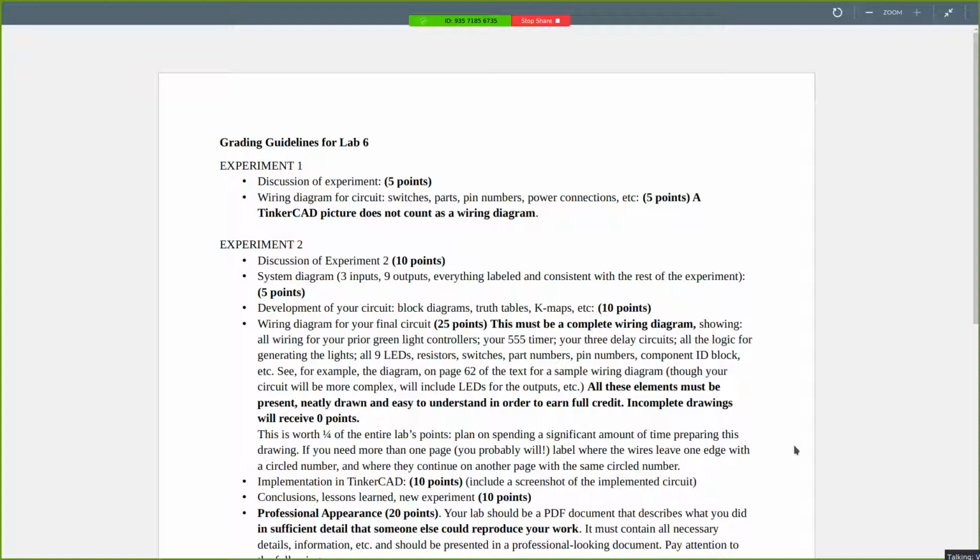I mean, when I had it disconnected from the 7-segment display, the counter itself, I tested it with the LEDs, and it would count all the way up to 1111, and then reset, and then redo the count again. So I guess it is Tinkercad. Well, no. If it's counting up to 1111, you're not resetting it after 9, right? And that 7-segment display, if you ask it to display 10 through 15, it just shows you a blank. So for 12 seconds, it'll look like it's not doing anything, but it is. It's counting, but it's designed to display nothing if the input is greater than 9.